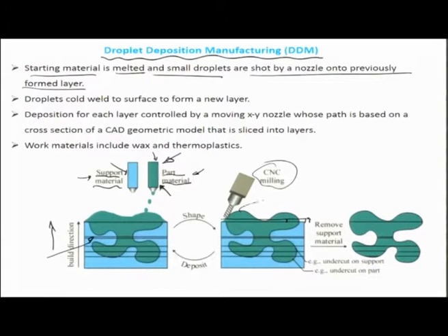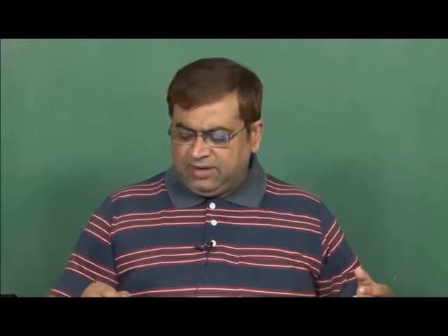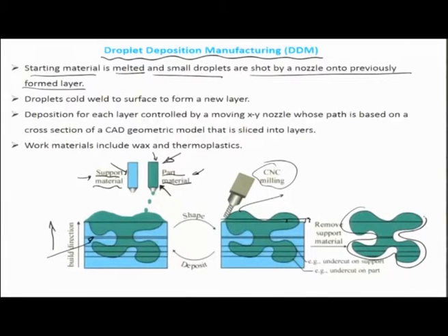So once this extra material has been shaved off, the layer is prepared for the next round of printing, where the next slice, which comes as information from the CAD package, gets laid out in terms of areas which are coated with wax and areas which are coated with a solid material. Obviously, in a layer by layer manner, a very complex part like this can be built, every time milling it and shaving it to the layer thickness that is intended.